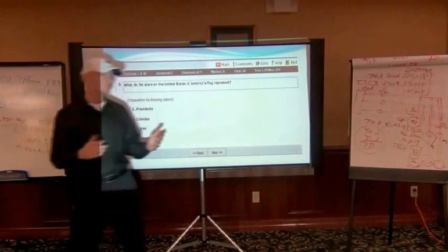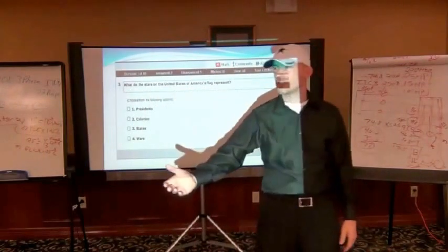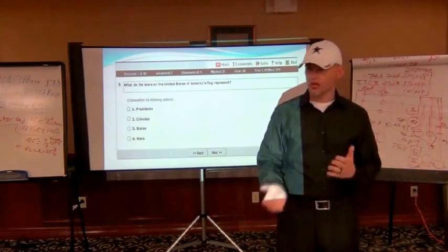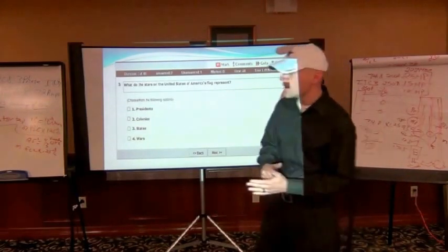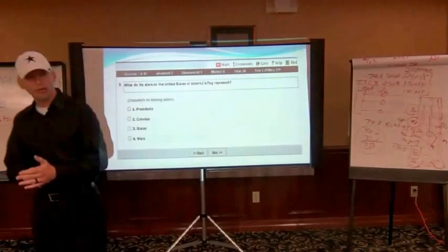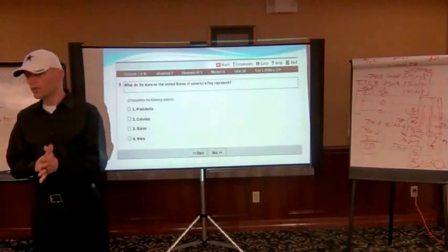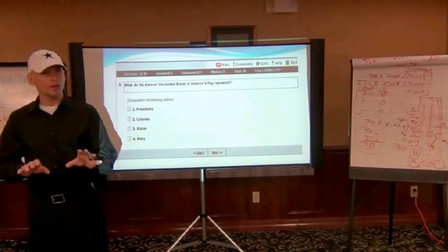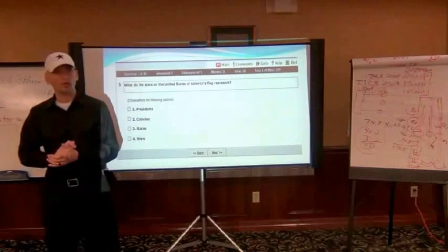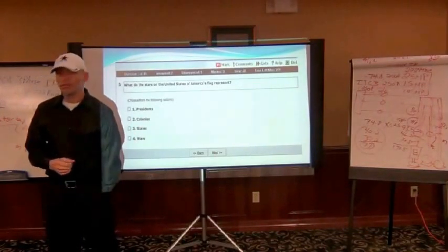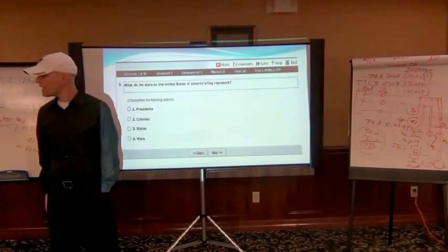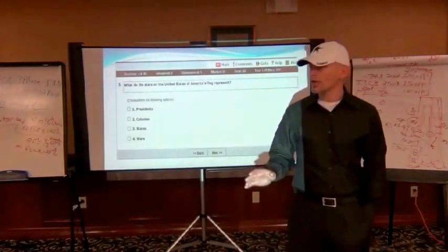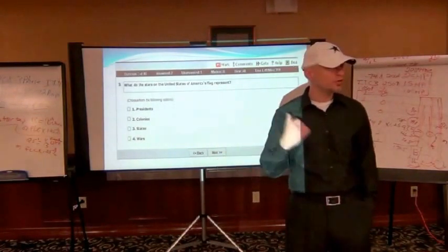Because how many times have you looked for a question, like say you're on question number 82. Well, not for you guys, you'd be on question number 62. And you're looking for the maximum size or minimum size ground electrode conductor for a rod, which is what? What's the minimum size for a ground rod? Not the jumper to it, but the actual ground rod itself, diameter. 5/8, right? You guys know that. That's one that you should just answer and don't mark it, just answer it and never go back. There's no point in looking up a question like that, because if you could tell me that, do it the same way on the test, right?